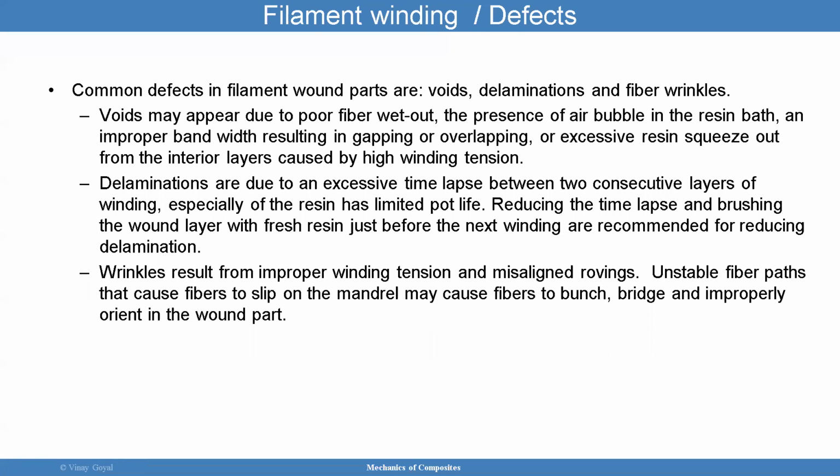Then you have delaminations that are due to excessive time lapse between two consecutive layers of winding, especially if the resin has a limited pot life. Meaning, I did one layer one day and then another layer two days later. Well, you may have issues there.